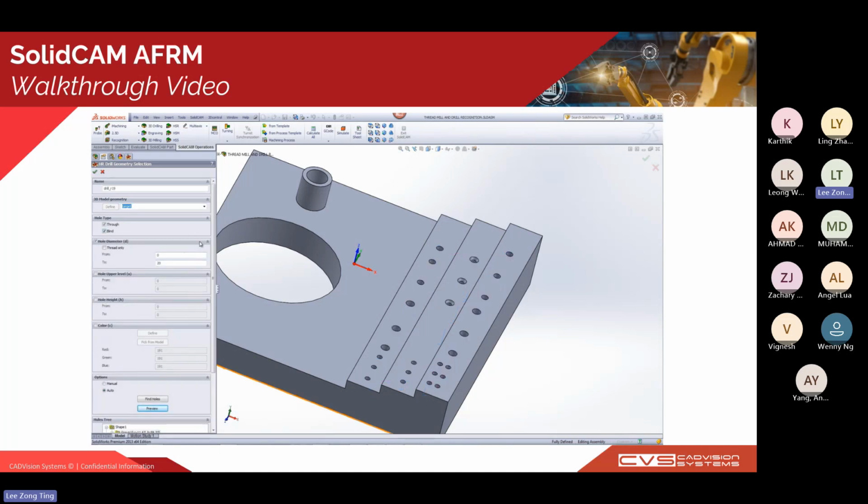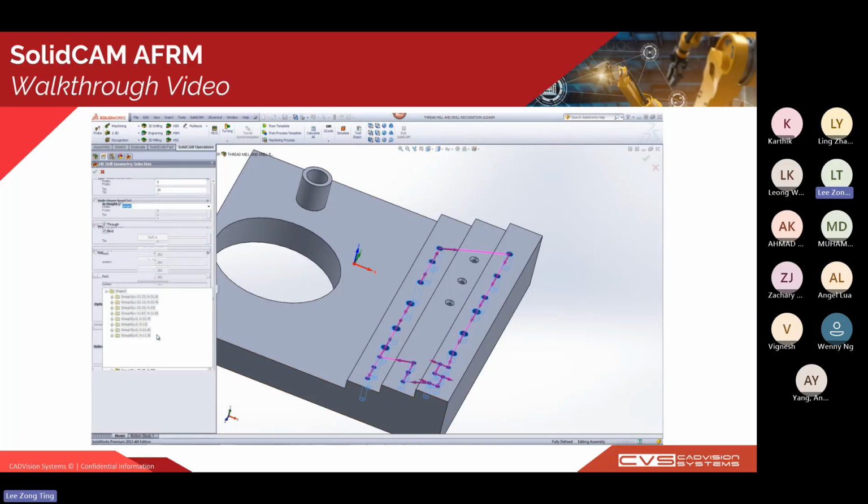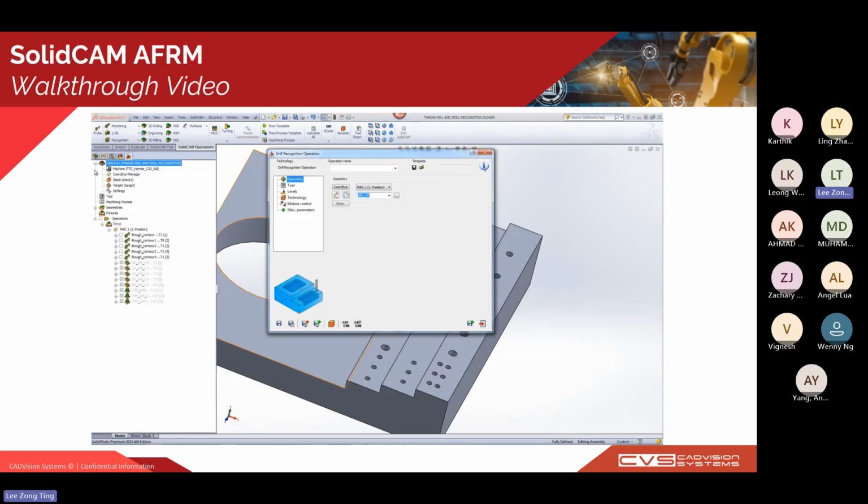So imagine you have a big 3D CAD model with different types of holes. You can easily find them using this. So go ahead and remove this hole because we don't want to do these operations for this type of hole. And after we are satisfied with the holes that are found by the system, we can go ahead and specify the drilling technologies we want, the tool we want to use, and simulate it.